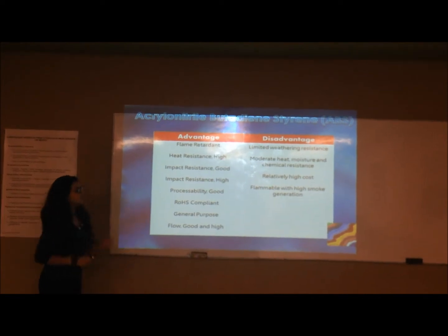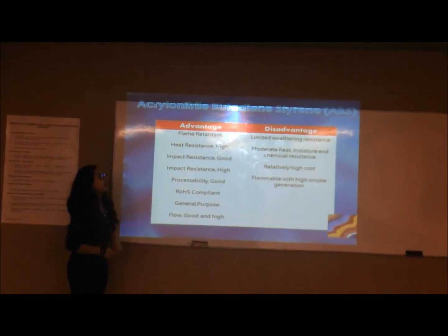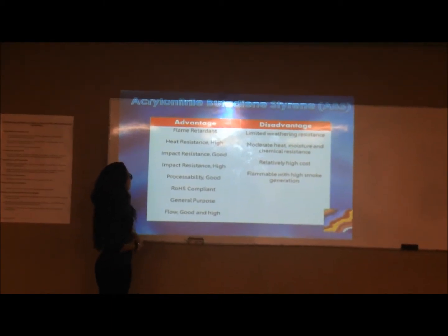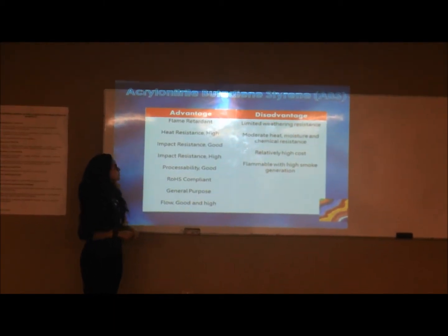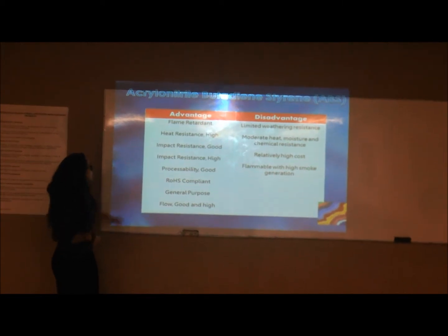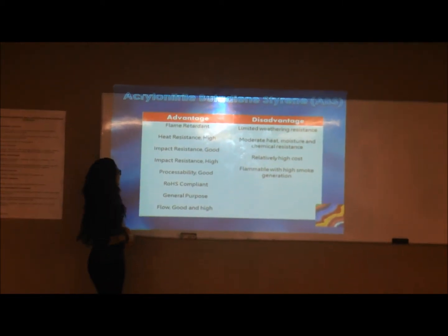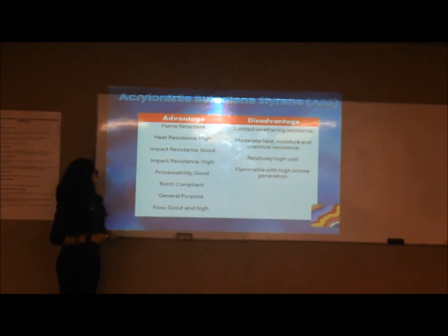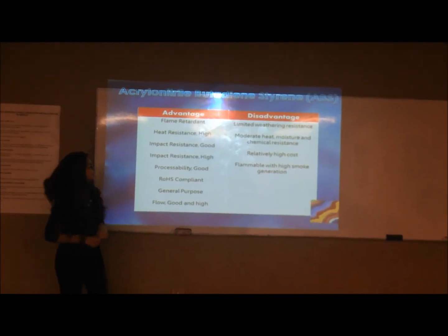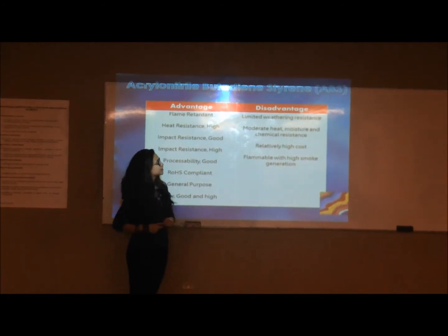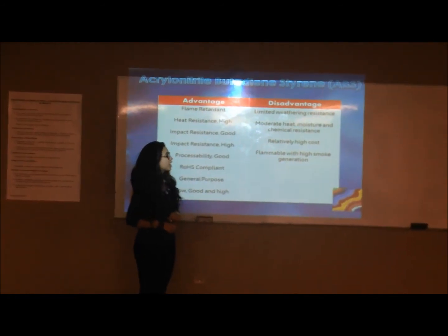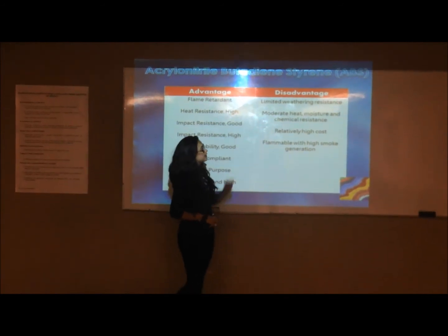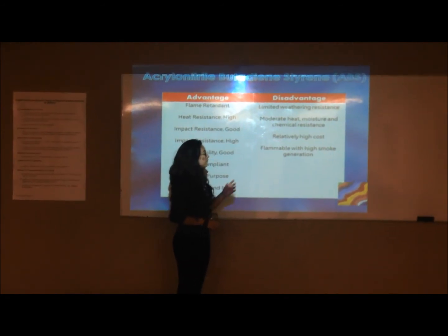And now, in the ABS, we have also advantages and disadvantages. In advantages, we have flame retardant, heat resistance that is high, impact resistance that is good, processability, compliant, general purpose, flow, good. Okay? And disadvantages, we have limited wearing resistance, moderate heat, moisture, and chemical resistance, and a relatively high cost, flammable